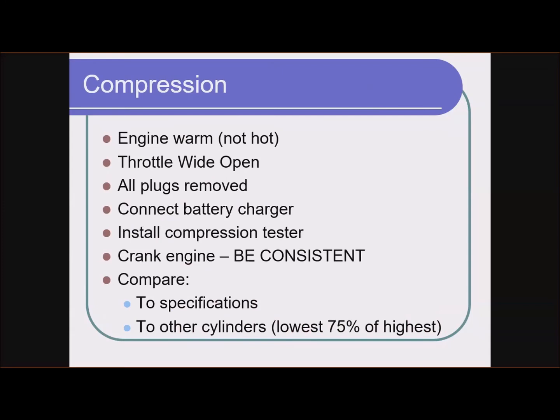But for the most part, if we're doing a full-on compression test, removing all of the spark plugs will make it real easy for the starter to crank the engine over. It will put the cranking speed where it belongs for the compression test, where with them in, it'll be cranking slower than it should. And it's much easier on the battery, much easier on the starter.